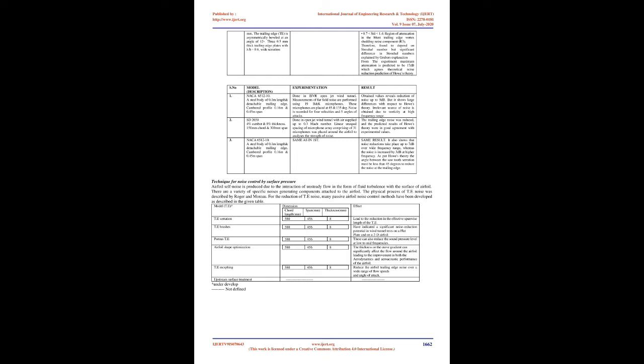The primary role of the porous metal foams in a Poroserrated trailing edge is to suppress the vortex-shedding tonal noise. However, an optimum selection of the porous material is also found to be able to further reduce the broadband noise level. The new serrated trailing edge concept developed here has the potential to improve the industrial worthiness of the serration technology in achieving low noise radiation in fan and turbine blade.